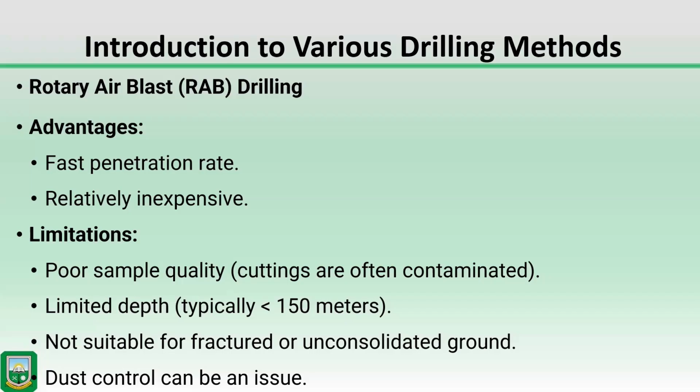The rate of penetration will reduce, and we will have a lot of choking. The drill rod will have a lot of choking because of the presence of the cuttings within the hole. And so we need to remove the cuttings from the drill hole. And since the compressed air is not giving us that because of the presence of fractures within the hole, our work is going to be difficult. It's very, very important.